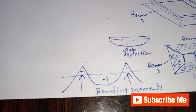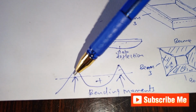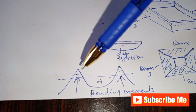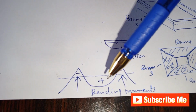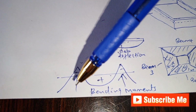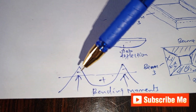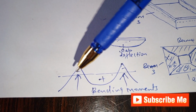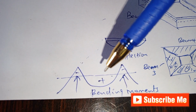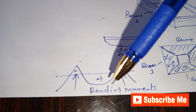Therefore, the moments on a two-way spanning slab. This is the beam, this is the beam. The beam tends to act upwards, while the slab tends to act downwards. So the beams will cause what we call negative bending moments because they tend to act upwards, as compared to the slab, which tends to act downwards and results in positive bending moments.